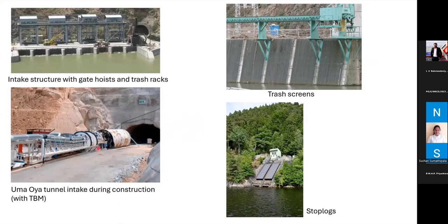Build the tunnel in parts where we have good cover and good geological conditions, as well as maintain the intakes with good trash screens and stop logs to avoid any debris going into the reservoir and the intake, which can result in damage in the longer run.